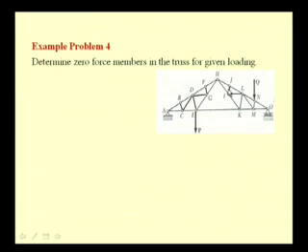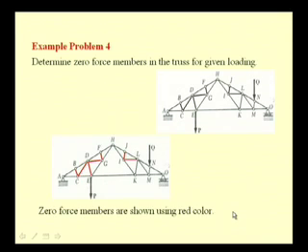And if we analyze this joint I, we can find that IL is also a zero force member. So, all these zero force members are marked in red in this picture. And once we have determined these zero force members, now if the problem was to determine all the internal forces of the various members, then we can only consider those joint equations which result in determining the various unknowns.